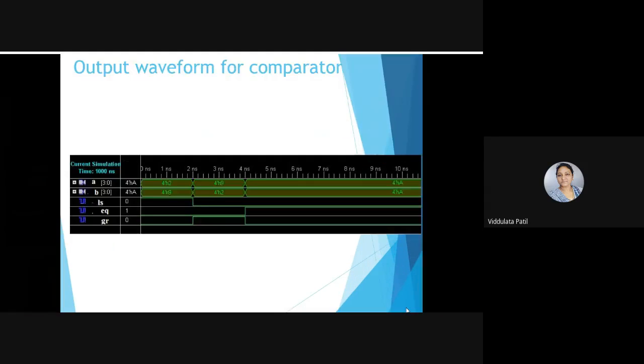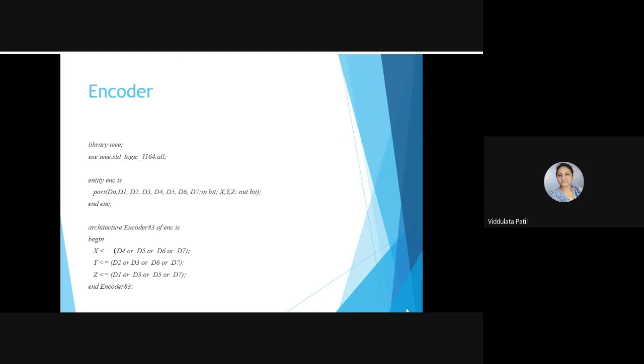So now let us check it. I hope you have written this code in this manner. First, the library declaration. Which library do we need to declare here? That is IEEE. And the package that we are adding is std_logic_1164. All the functions available in this package are added in this code. No other package is needed; these two are sufficient for this.